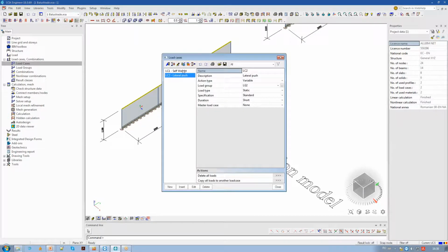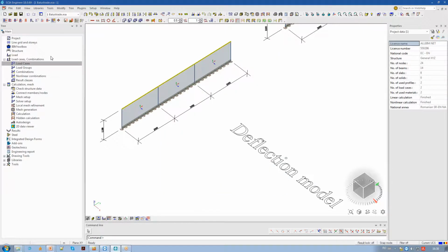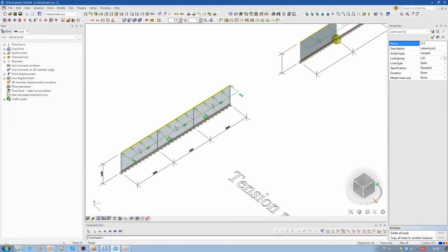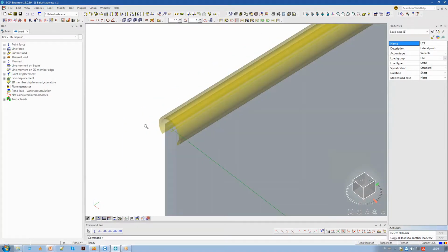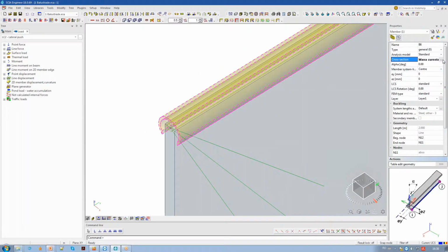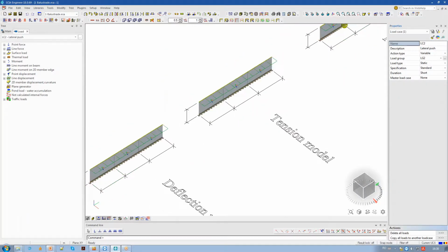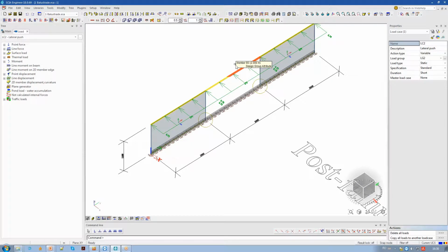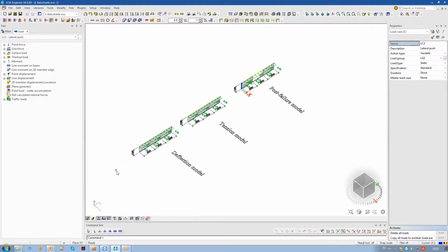So we go to the load case. Something simple. I just inputted here the self weight, calculated automatically by the software, and a lateral push of 0.75 kilonewtons per meter that acts on the steel railing. This is a steel element that simulates the handrail, and it also has a structural load. So when the glass fails, this steel element needs to be strong enough to transfer the loads to the adjacent panels.